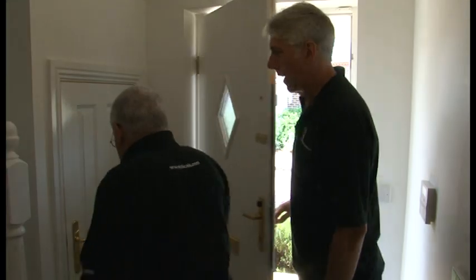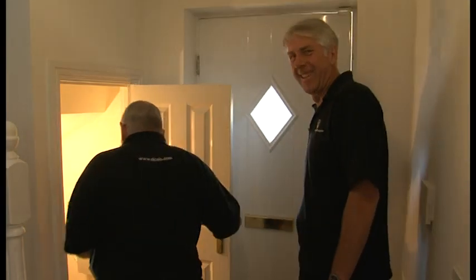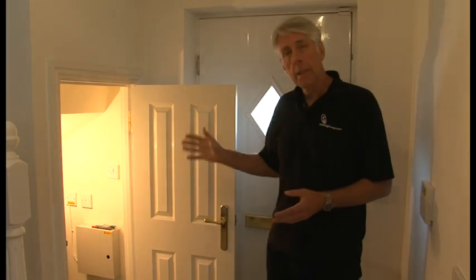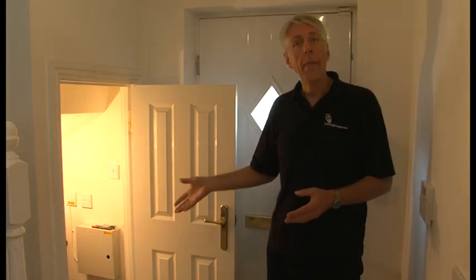To your cupboard, Mr. Cable. Thank you. Tony's already done some preparation work in the house, and all the lights have been turned on everywhere. We've also unplugged any appliances to avoid any sockets interfering with later live testing. So now what we're going to do is turn off all the breakers and then bring them on one by one and find out which circuit that breaker energizes.